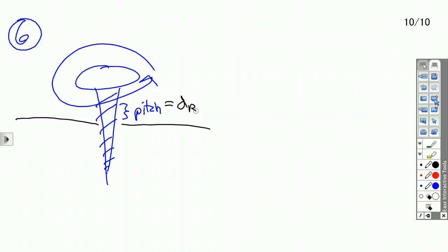Your effort distance, while I'm on this, your resistance distance, however much that is resisting, usually with a lot of friction, that's going to be your resistance force, is how hard it is to do that. It'll be, again, in the same direction, parallel. So your effort, though, you're not literally pushing that straight in like a wedge. You're turning this and using the inclined plane to do that for you, the inclined plane that's wrapped around the cylinder. So it's more like a wheel and axle.